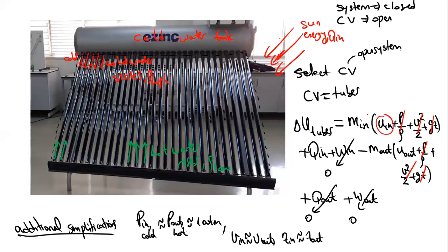So why is internal energy the main player here, as well as this Q in? It is the important part, because this internal energy that leaves the system is proportional to temperature. And these types of systems have more temperature change than pressure change.